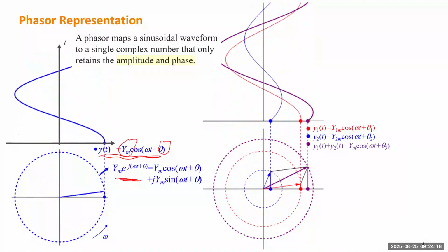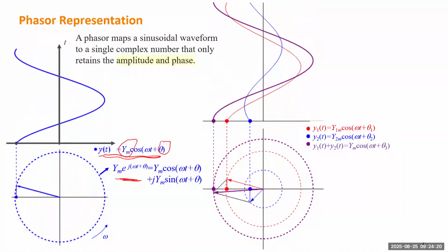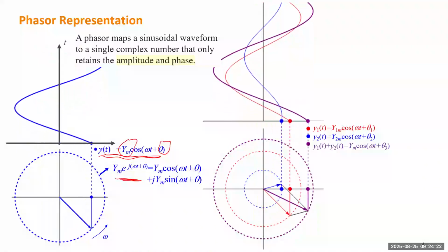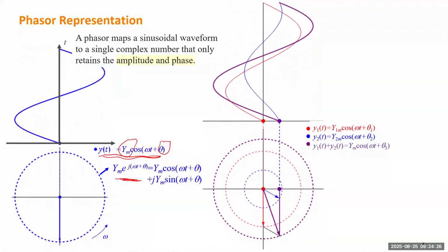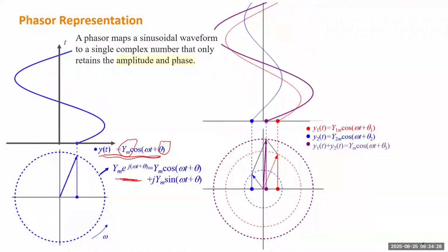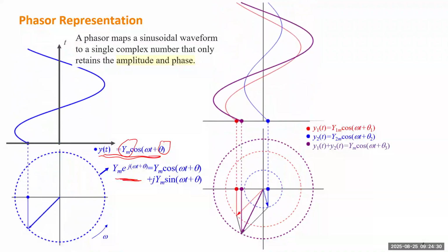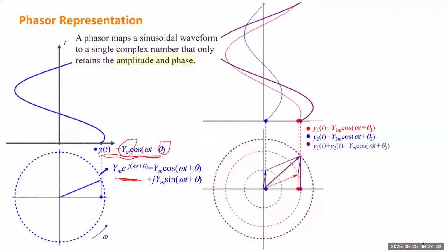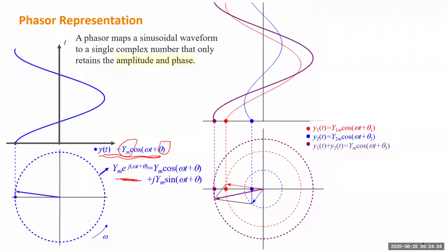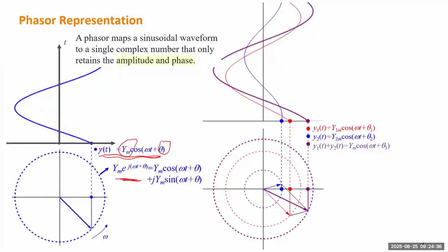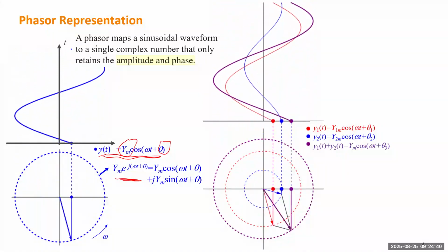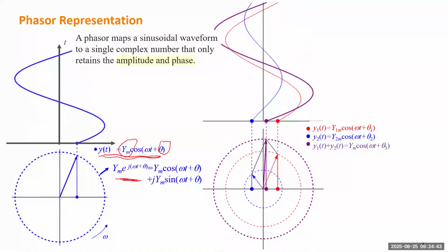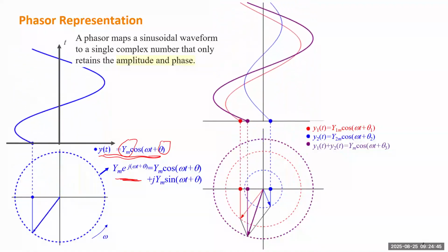This is very convenient if you have 3 waveforms that are all synchronized at the same frequency, maybe one indicating a current and the other two indicating voltages. To do such calculation, either we use all 3 waveforms in every expression, or we treat each waveform as a complex number.